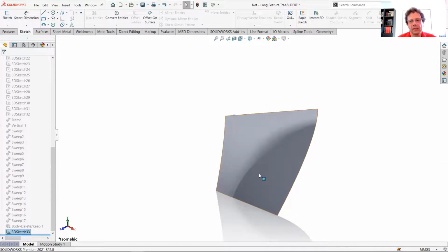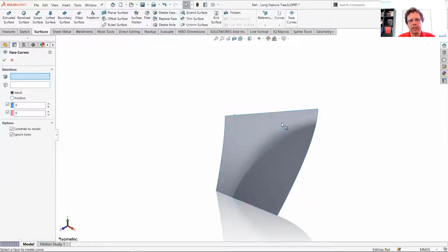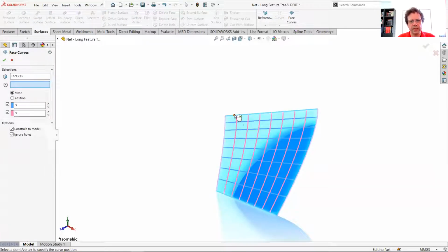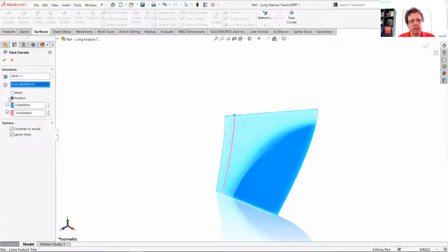Next. So by the way, I created this point and I want SOLIDWORKS to pay attention to this. So Mr. SOLIDWORKS, come and watch. You see, that's step number 1. You do one sketch with one point. And let's call this vertical path for my sweep feature. Okay, good. So this is the one. Let's create now a guide curve that's going to go through this point. So select the face, select the point, pick only the pink one, and click OK.